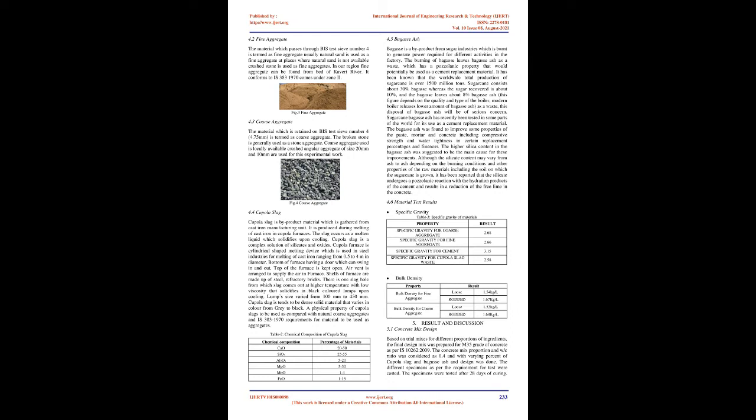Also, the above results show a beneficial application of the use of sugarcane bagasse ash, reduce the environmental problem, and minimize the requirement of landfill area to dispose sugarcane bagasse ash. They concluded that there was a considerable increase in service life of the concrete structure and reduction in heat of hydration. Material and properties. Cement.